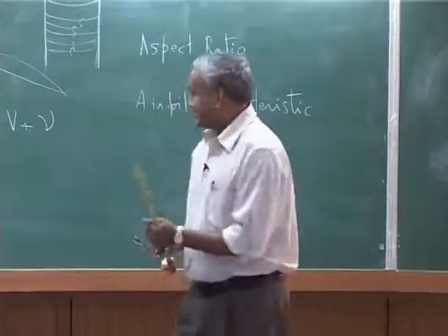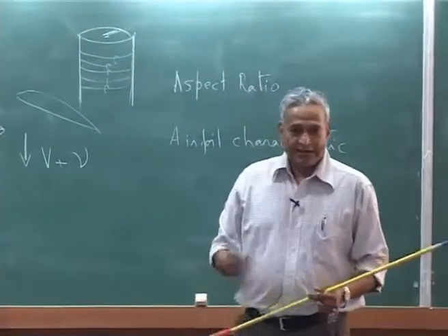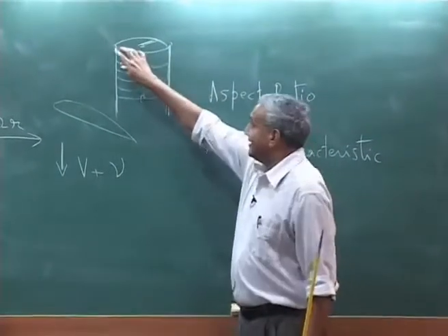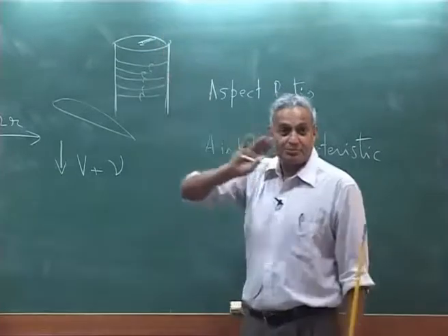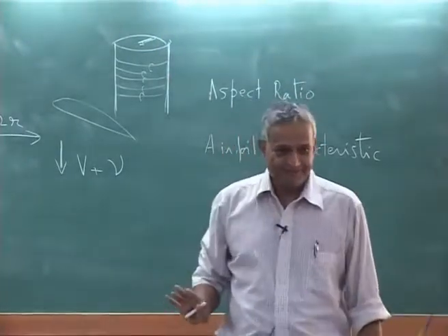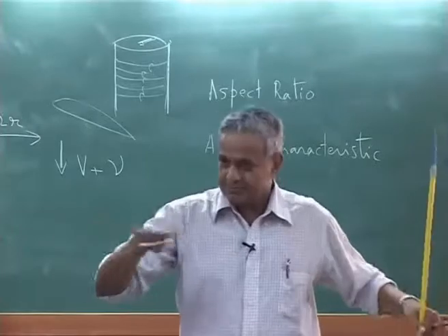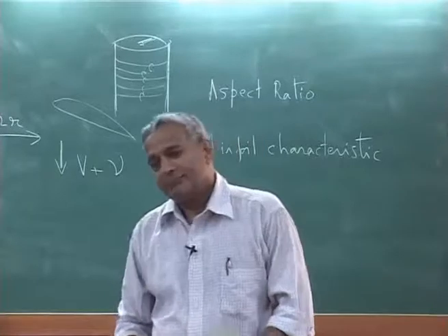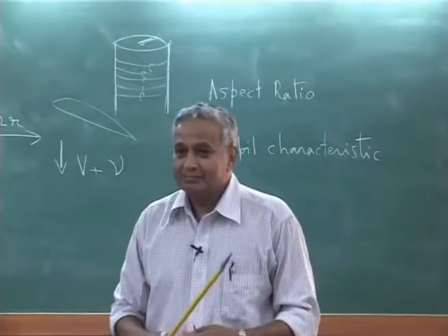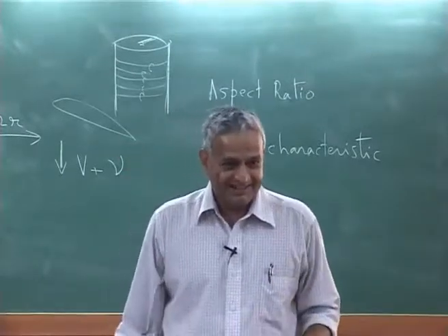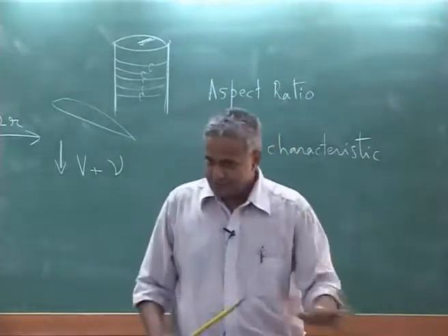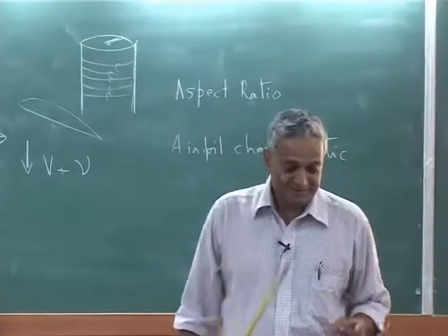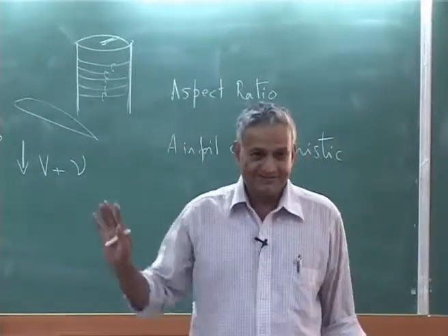When you use a cylindrical wake like this, the induced flow calculated by this approach at the rotor disc is the same as momentum theory. Uniform loading, uniform thing you take, then you get the same result. So, momentum theory is not all that bad. We use momentum theory in this course. Please understand, momentum theory is even today used in research.